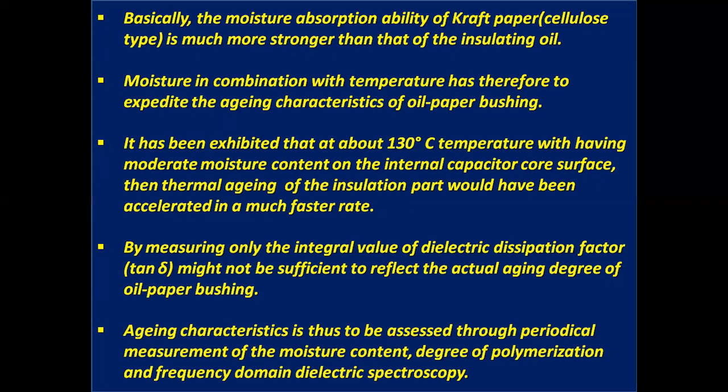It has been exhibited that at about 130 degrees centigrade temperature, with moderate moisture content on the internal capacitor core surface, thermal aging of the insulating part is accelerated at a much faster rate.